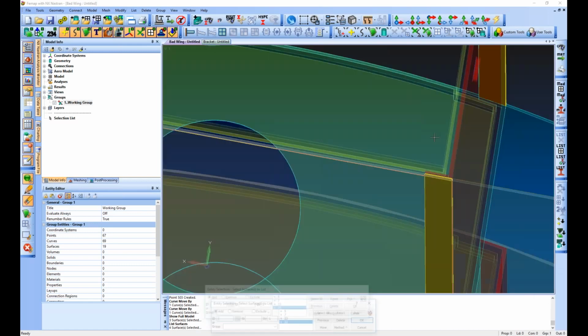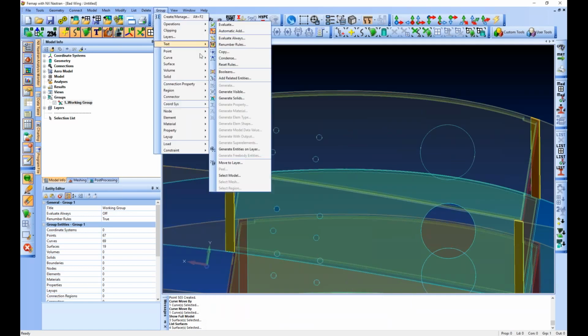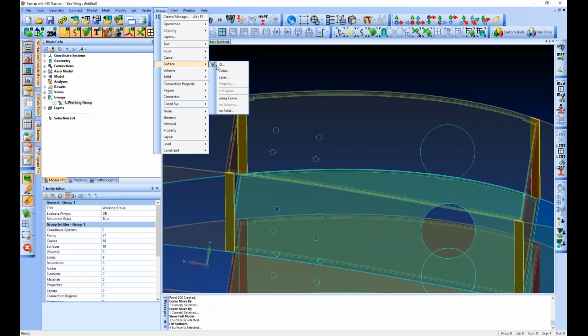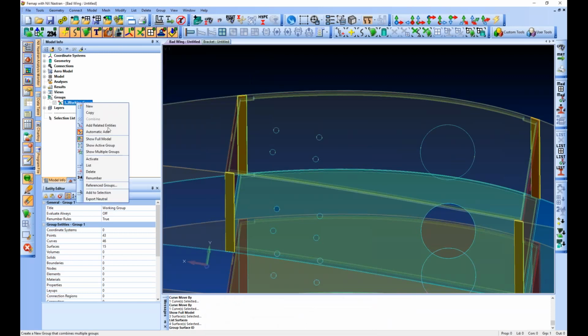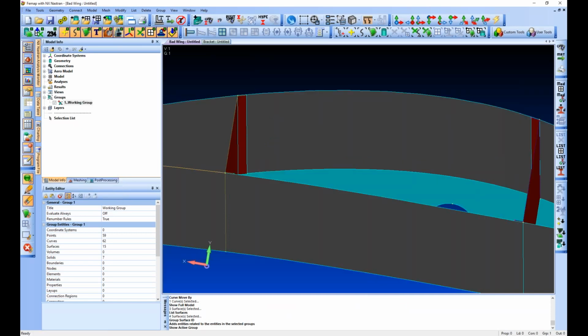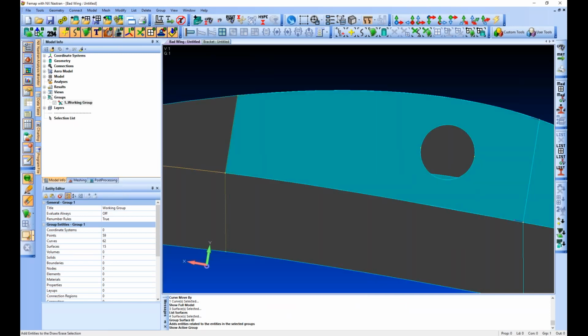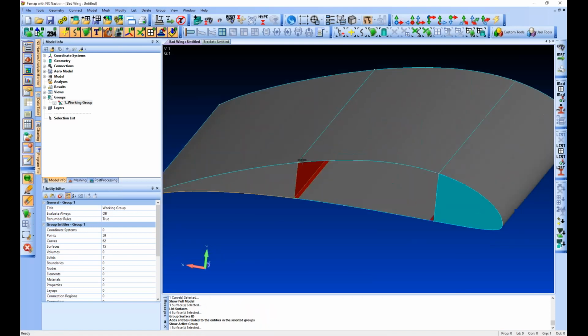So now we have these 4 surfaces. I'll just copy, and then using the group surface ID, I'll paste those in, and it's usually good just to add related entities. That's going to bring the curves, the points, everything in there so it's easy to work with. And we'll just go back to our active group and close this tool to make sure not to miss something. And actually, I probably don't want that there.